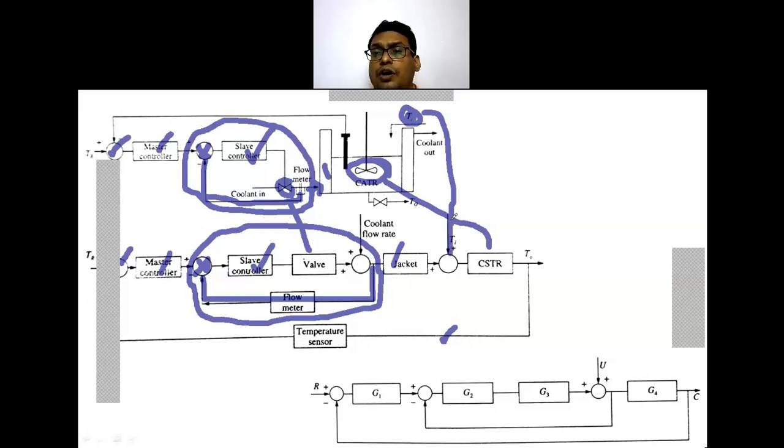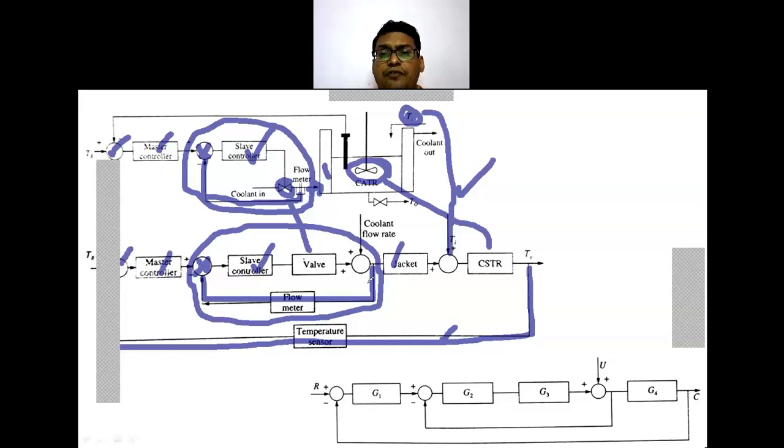In the case of feed forward control, we can measure this and apply the feed forward control system also. So this outlet temperature is measured, sensed with the thermometer, and that goes to a controller comparator. So this is my outer loop. That is why we observe in the block diagram there are different loops inside loops, because of either this cascading effect or the feed forward effect. As we are making the systems more and more robust, they become more and more complicated and difficult for processing also. So one has to optimize on the parameters which are of more concern and take a proper decision based on that.